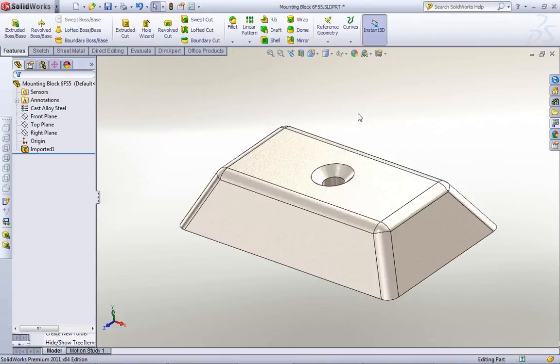You can make drawings using your assembly. So really, again, if all I need to do is change certain things or 25% of it, even if this was a native SolidWorks part, for some of you who've been using SolidWorks for many years, if you go back and you have a very large component that has a lot of features, some complexity to it, if you go back and edit some of those things in any modeler, you risk the odds of it breaking something down below it. The parent, if you change the parent, the child might change. So that's the same in SolidWorks.